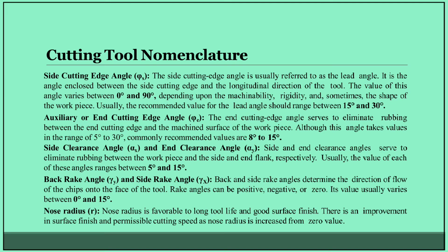Next one, back rake angle, gamma y, and side rake angle, gamma x. Back rake angles and side rake angles determine the direction of flow of the chips onto the face of the tool. Rake angles can be positive, negative, or 0. Its value usually varies between 0 degree and 15 degree.